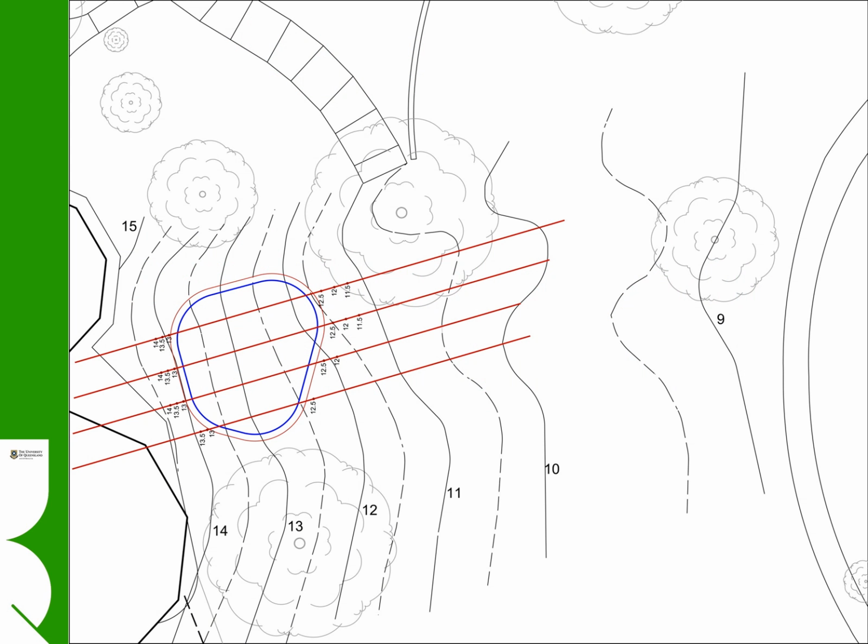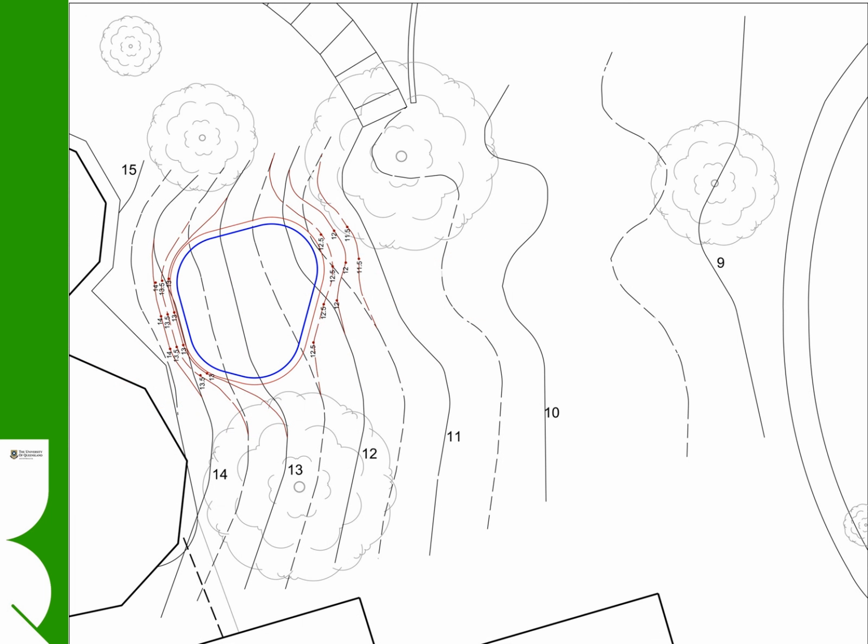By lining up the section lines with the new spot heights marked on them, we can follow a similar procedure to generate our contour plan like we did in the first instance. We will connect the new points around the pond, and at the end we will draw a line of best fit that connects the end points of our section line with the corresponding existing contour. We need to blend the new and existing line smoothly so that the ground profile maintains its flowing characteristic.